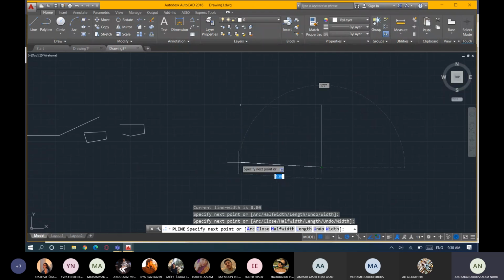It will help me to identify the end point of this line that is exactly at the same point as the upward one. You see, I can automatically identify the end point of that line without giving the dimension exactly as the previous line I have on the top, with the help of those icons, object snap tracking and object snap. Okay, so now I can automatically go there and click it.